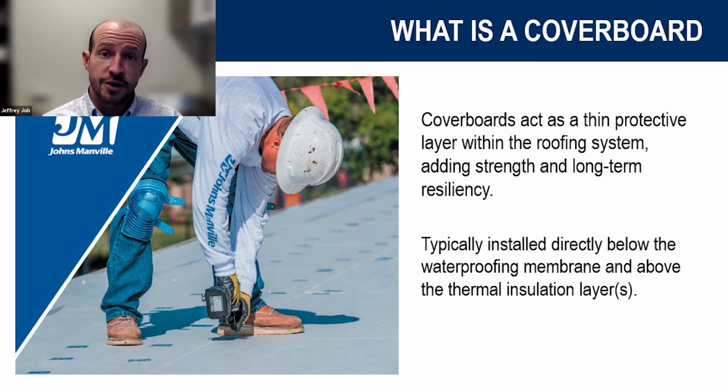A key thing with a coverboard is really just a resilient layer to add to your system to help protect the two main cost buckets of your roof system. That might be kind of a weird way to put it, but really it's a protective layer that's protecting your insulation below, and it's protecting your membrane above. So any roofer is going to be pretty aware of that.